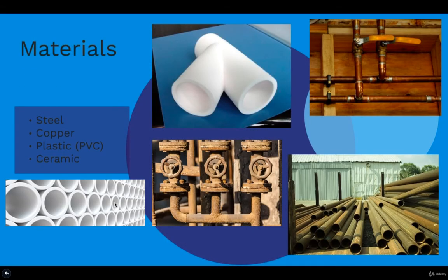Now, what type of materials do we have? Okay, we already understand what pipes are. They are typically long. So the most common one will be steel, typically used in the chemical industry. But we also have copper ones. Those are used for natural gas, maybe in home applications or more specific applications. This is very expensive compared to traditional piping.